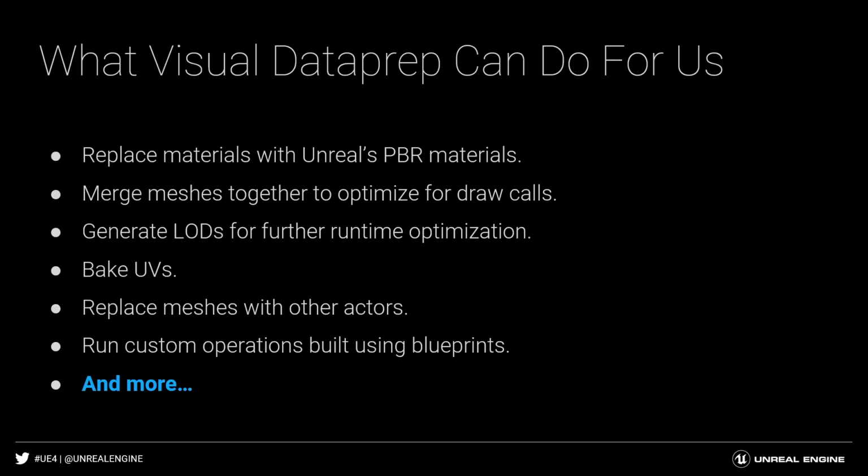Now here are some of the things that the Visual Data Prep tool can do for us. Users can do things like creating LODs, setting up lightmap UVs, substituting materials using material data tables, deleting and merging objects, and this will help to optimize your draw call count. And it can do these things based on selection factors like object class, object name, metadata tags, layers, tagging, and a lot more. And the other cool thing about it is that users can create custom functionality. So you can create custom selection filters as well as custom operations using Unreal's built-in blueprint system.